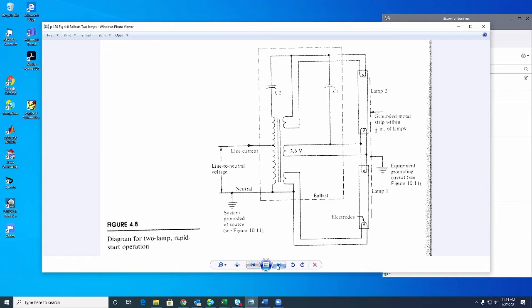So what they do in lamps, probably the best way, would be to use three-phase systems or two-phase systems so that the zero crossings do not occur at the same time. Okay, so then there are two lamps and they don't have synchronous zero crossings. So while one lamp is low, the other is high. So that gets away with this effect. Okay, so then we can use three-phase.